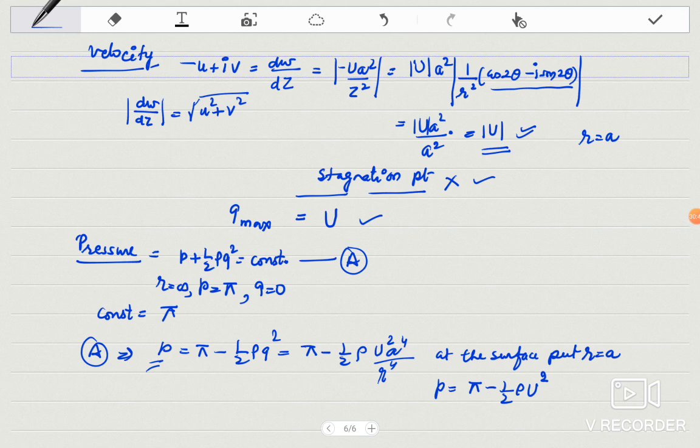Now here we can discuss an important point, how will we prevent cavitation. Actually, if this is a cylinder and this is the direction of the pressure, it is necessary to prevent cavitation that this contact should be there, and this contact will be there if p is positive, because in the inward direction p is taken as positive.